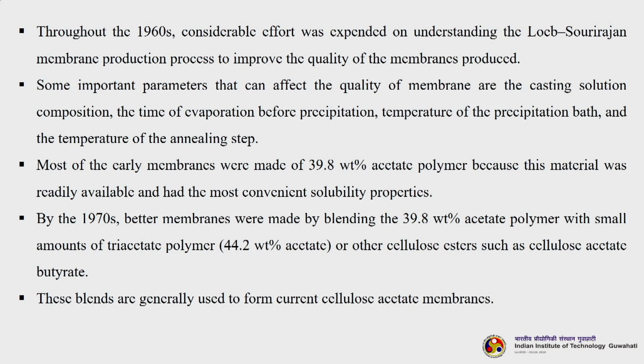Throughout the 1960s, considerable effort was expended on understanding the Loeb-Sourirajan membrane production process to improve the quality of the membranes produced. Some important parameters that can affect the quality of the membrane are the casting solution composition, the time of evaporation before precipitation, the temperature of the precipitation bath, and the temperature of the annealing step.